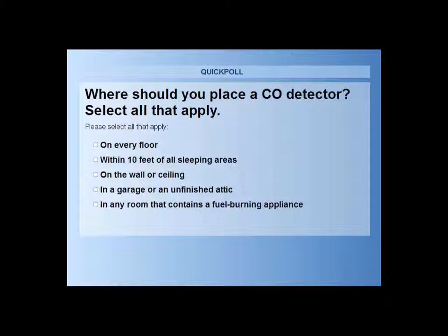Justin and Doug, we do have a couple of questions posted, and I know we're going to hear from Doug here in a moment. Justin, the first one is after a carbon monoxide event. If a home or residential multifamily application does have a CO incident, what happens to that CO cell? Does it need to be replaced, or can it be reset once the air clears? Once the air clears, from our products, the CO TTR and our common detector, the device can be used again. The CO cell that we use does allow that, so the device does not need to be replaced at that time.